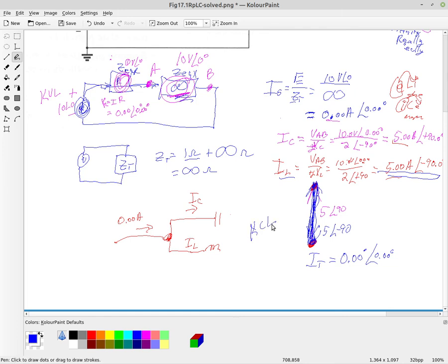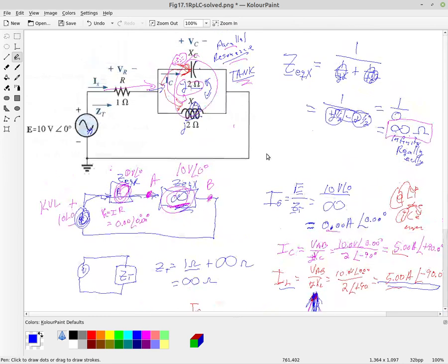All right, so again, this is a special circuit here called a tank circuit, which uses parallel resonance, where the reactance of the capacitor has the exact same magnitude as the reactance of the inductor. And so we do have current flowing through the capacitor and the inductor. These guys are sitting here passing their energy back and forth. Okay, but there's effectively no current flowing through this resistor here. Okay, so this tank circuit looks like an infinite impedance.